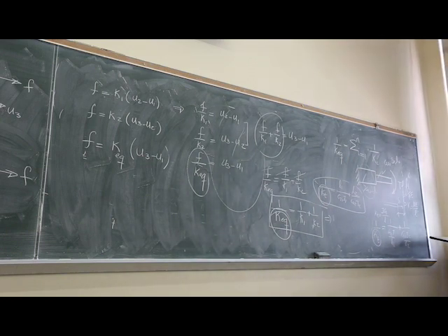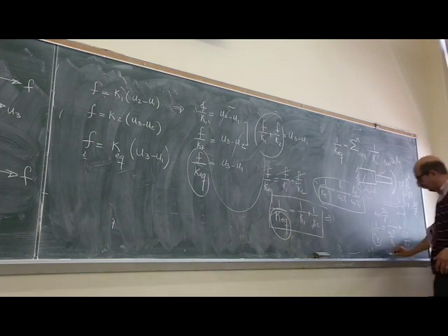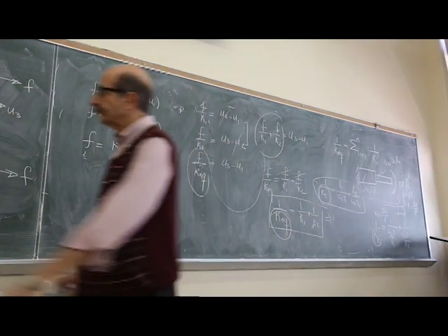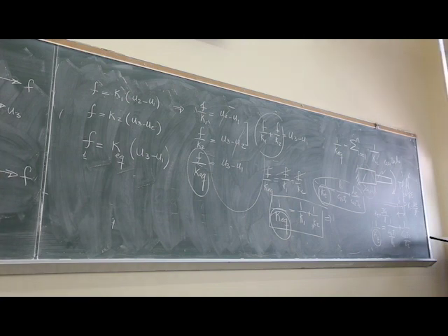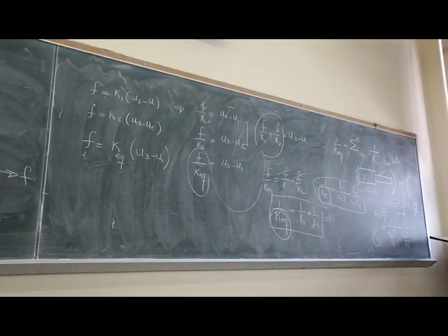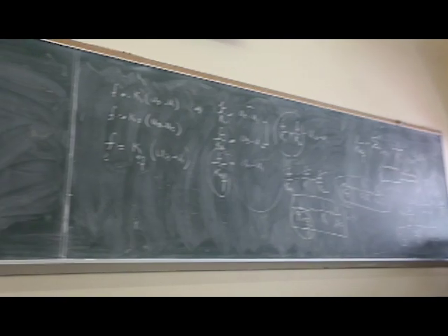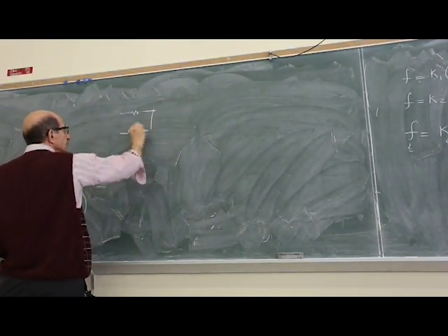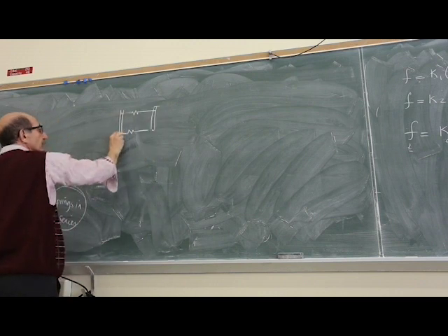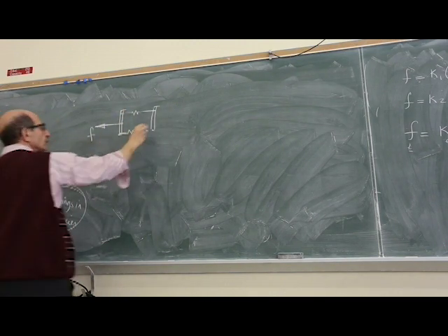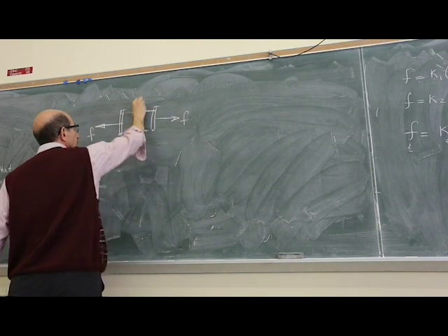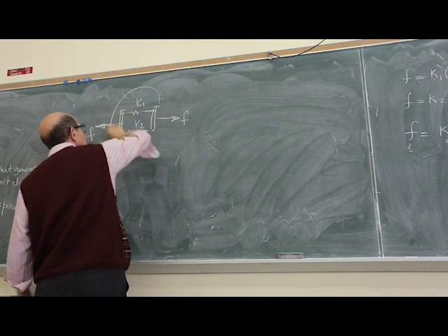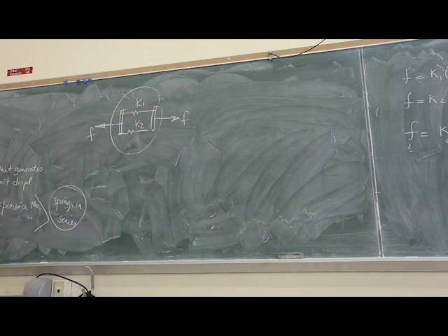So that's the definition of springs in series that you come across in many cases. But what does parallel mean? Parallel means that the springs or the stiffnesses experience the same deformation. In other words, let's say you have these two springs like this, subjected to a force, but the stiffnesses are different, and you want to replace these two with a single spring.